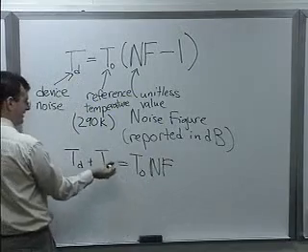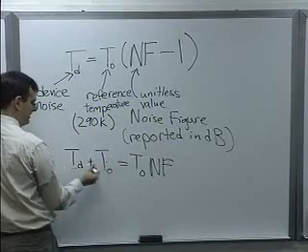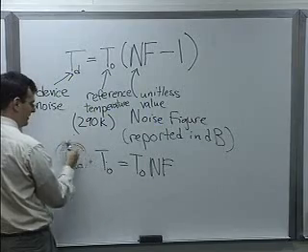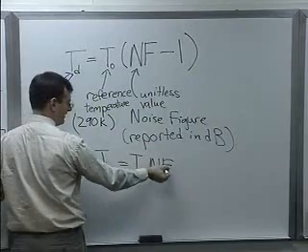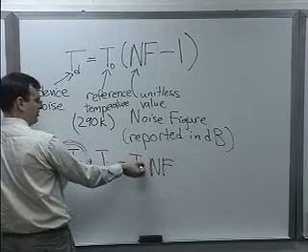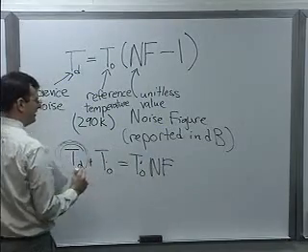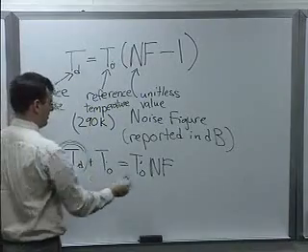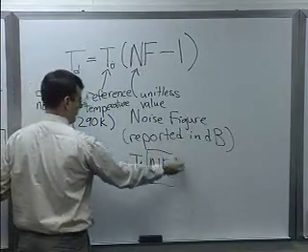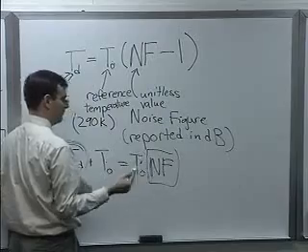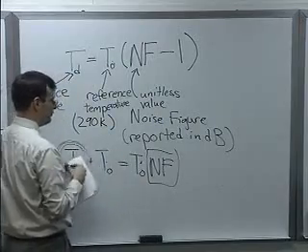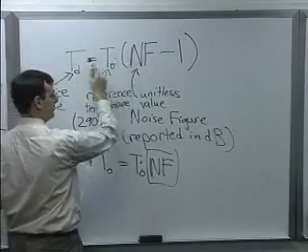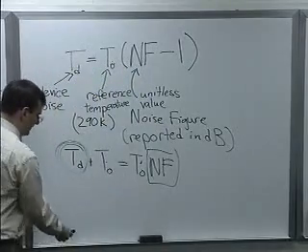So I take this much noise and put it into my device. I get this much added in terms of noise device temperature, and that's effectively like amplifying the original noise that I had. So you always have to specify a reference temperature to describe this noise figure term, the way that noise is amplified through a system. If you do that, then you can convert easily from one to the other. But engineers like that noise figure term too.